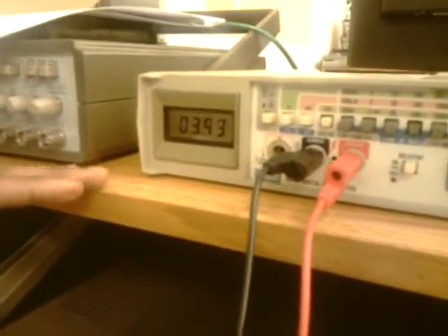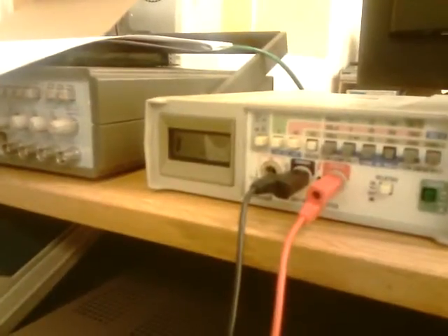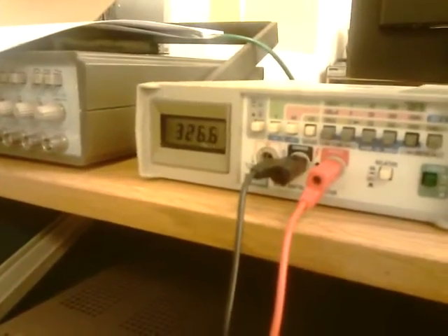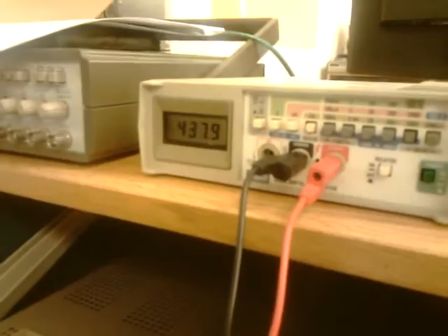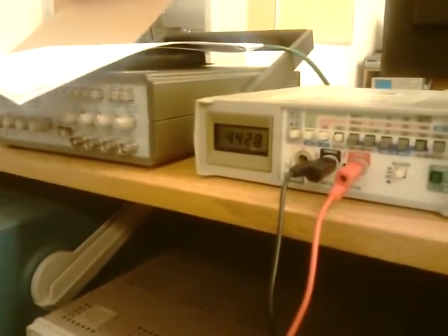So right now, this is normal room light, so the resistance goes down. Now I'm going to use my hand to cover this, and the resistance goes up to 2000 kilo ohms, like 245, about 400, and still going up, like 470 kilo ohms and all that. So that is how the LDR works. It works on the principle of light. When there's light, the resistance goes down, and when there's no light, the resistance goes up.